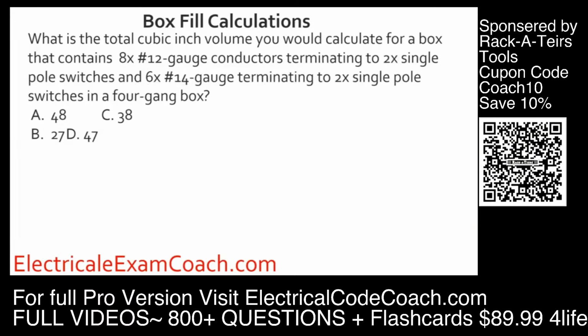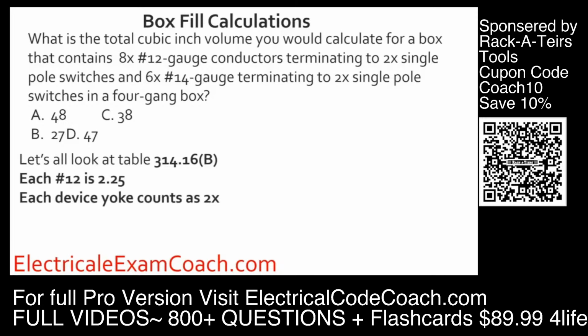What is the total cubic inch volume you would calculate for a box that contains 8 12-gauge conductors terminating to 2 single pole switches, 6 14-gauge conductors terminating to 2 single pole switches in a 4-gang switch box? This looks like a tough question, but I know that you can do it. First, we're going to head to our table so we can get our values. We know what each 12 is, and we know that each device yoke counts as 2 based off the largest wire that's terminating to the device.